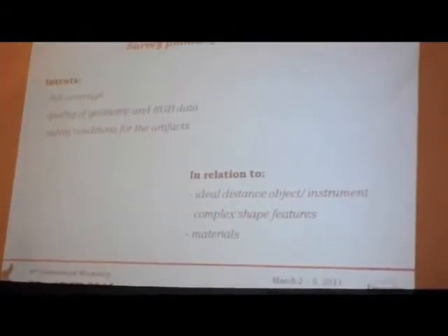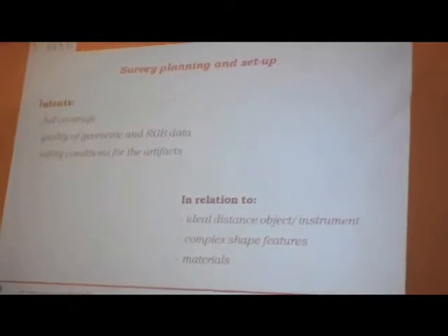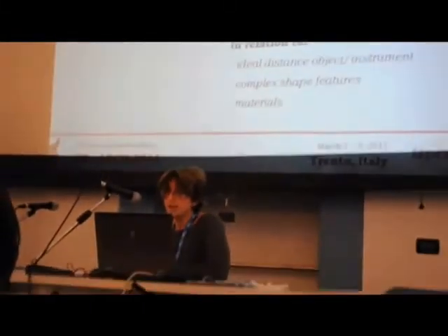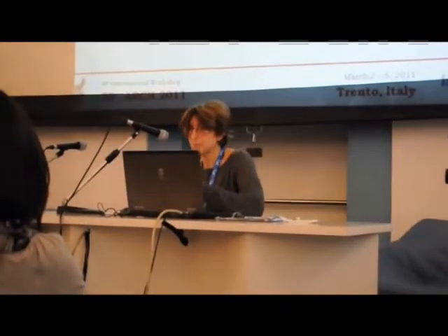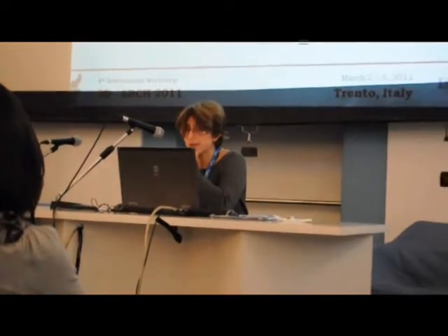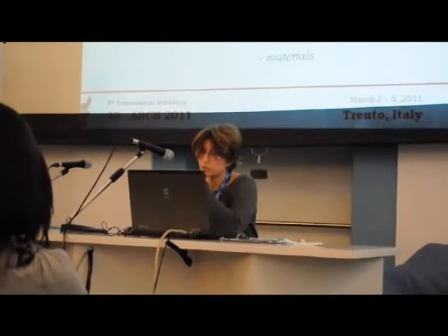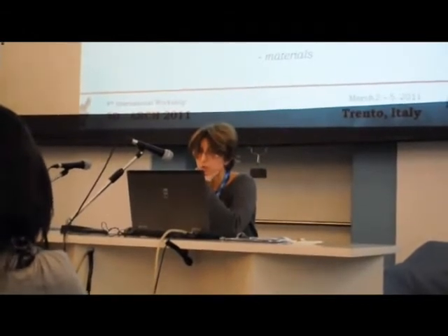The attainable results are based on this survey planning and setup. Decisions on the scanner software settings as range, distance, and resolution, and decisions on the placing positions and angles must be made minding these intents and in relation to these variables you see on the right.